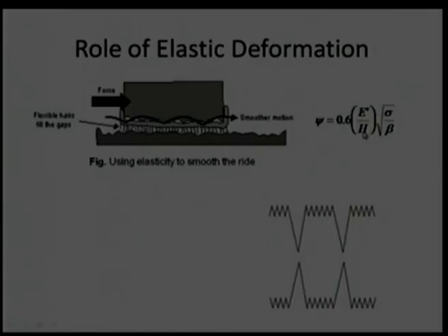That's an interesting thing. In addition, we have another parameter, hardness. Higher hardness will always be preferable. If you want a lesser wear rate, high hardness is preferable, and high hardness also reduces the plasticity index.